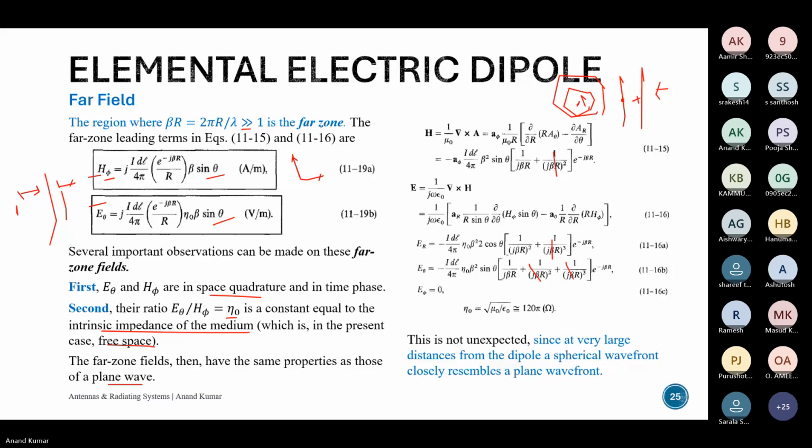When we say far field, for example 2 meters or 3 meters, we calculate the distance known as the far field, and we keep antennas at that place because if you're trying to illuminate an object, we make sure that we are doing it with plane waves. Some of you might be working with metasurfaces, and when you do measurements, you try to keep the antenna in the far field so that the metasurface is illuminated with plane waves.